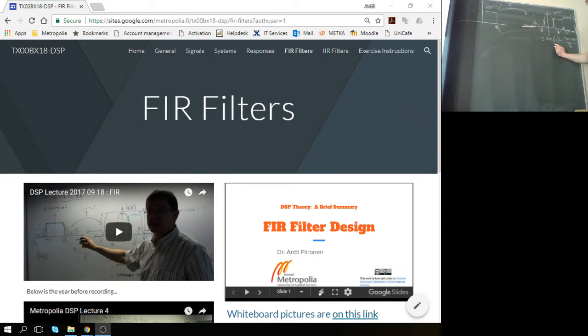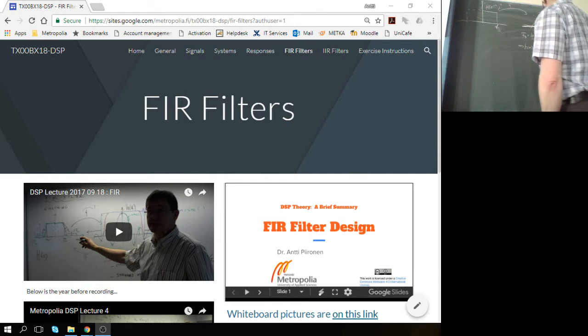And that one sample. In this case, the exact form of this one, if we have a sample rate fs, 1 over Ts, practically this follows the sampled sinc function, which is our h of n, following sinc of n times the cutoff frequency divided by the Nyquist frequency, where the Nyquist frequency is simply half of the sampling rate.